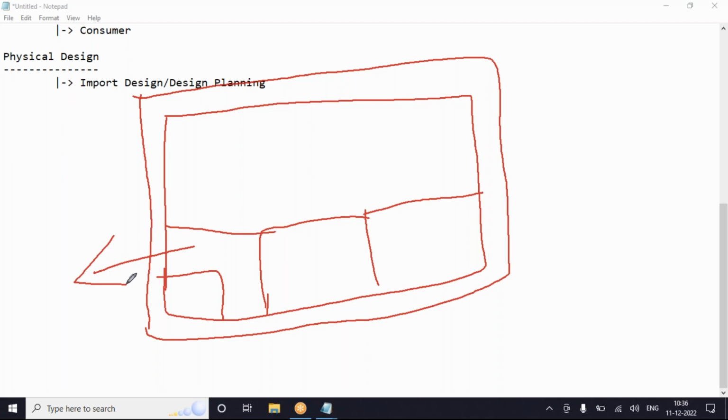Okay, let's say I'm the chip owner. I'll decide the shape. You do the camera module, you do the audio module. I'll share that particular shape and size with you. With respect to that shape and size, you are going to be designing that particular module. In later stages, I'll take your blocks and integrate them. Okay, this is what divide and conquer is.